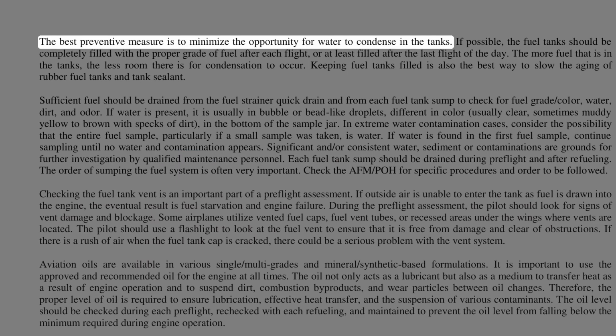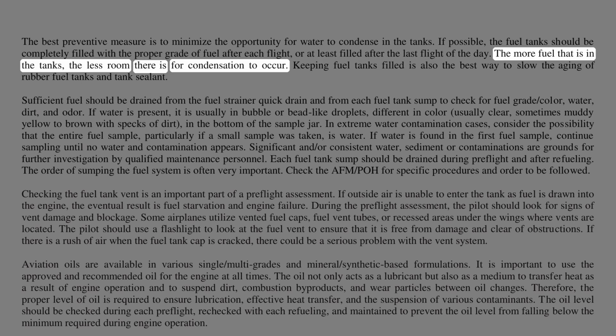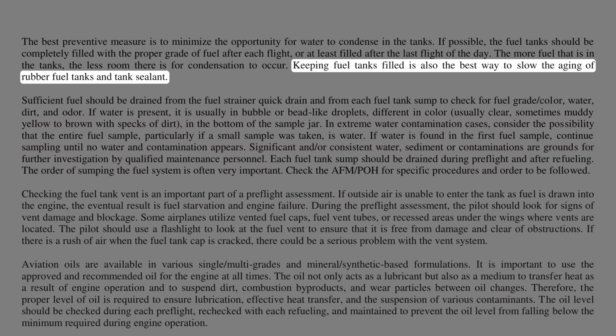The best preventive measure is to minimize the opportunity for water to condense in the tanks. If possible, the fuel tanks should be completely filled with the proper grade of fuel after each flight, or at least filled after the last flight of the day. The more fuel that is in the tanks, the less room there is for condensation to occur. Keeping fuel tanks filled is also the best way to slow the aging of rubber fuel tanks and tank sealant.